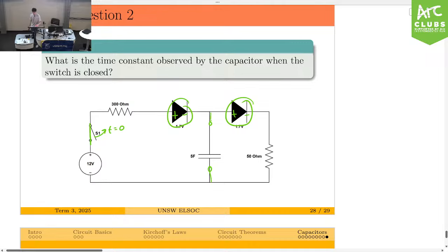What that tells you is that I'm checking RTH from here. This becomes shorted. Now these 2 diodes are also sources, essentially, so they get shorted. And so what you get, really, is, oh no, you don't get 1 loop, you get 2 resistors in parallel. Because what this pretty much comes down to is this.